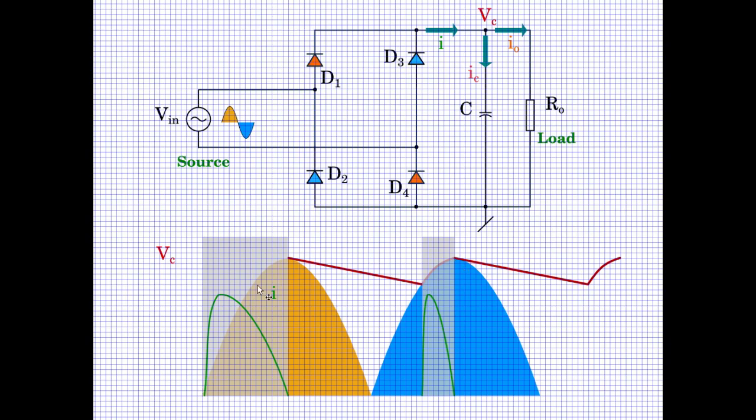Now this whole energy has to be made up. So you will probably land up with a current waveform at the first startup value, which would be much higher than the following steady state currents. So this may be the wave shape you will see from startup for the currents. But a problem could occur.